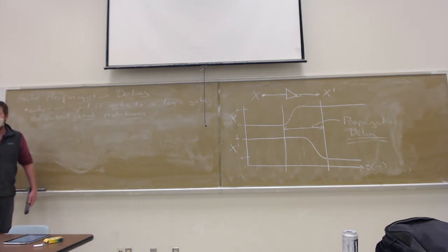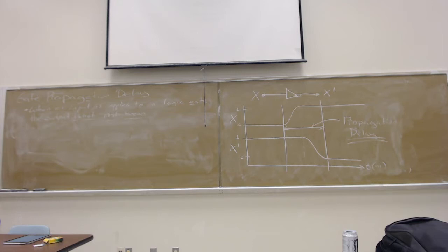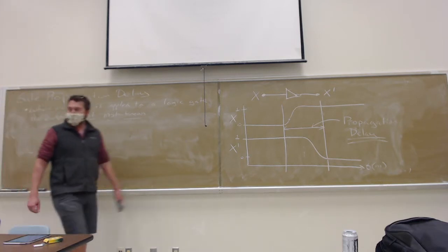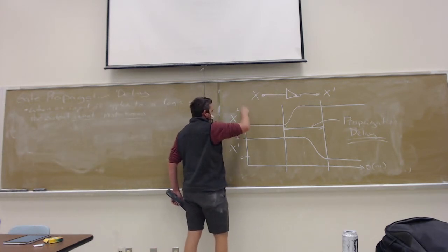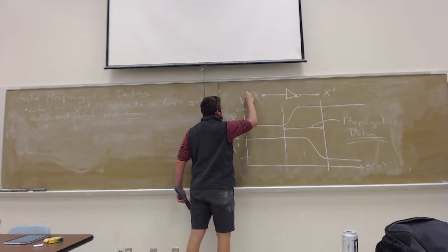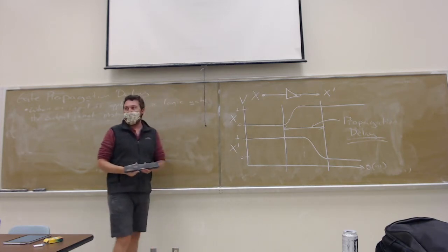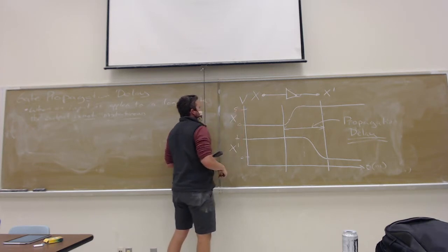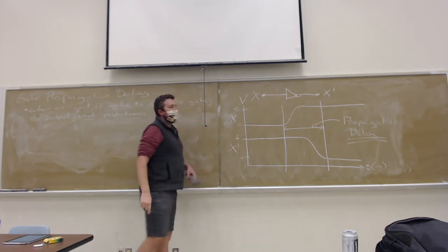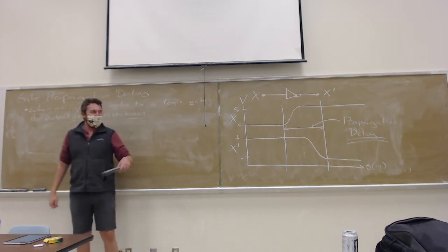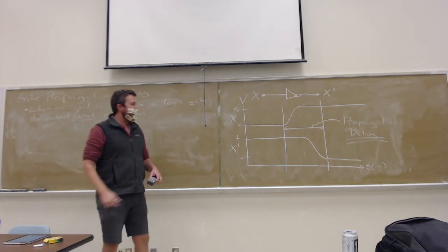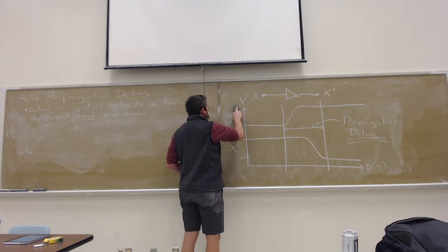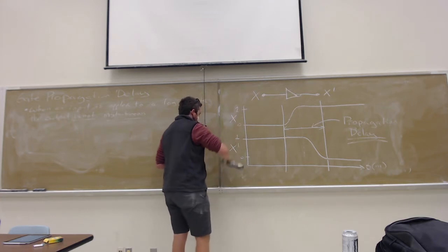So this graph right here is basically like the electricity going through the gate. Exactly, right? We don't usually label the vertical axis, but you could also think of it as the voltage on the circuit, 0 volts to 5. 5 volts is what's commonly used. It would absolutely translate over that, although in modern stuff, it's like 0 to 1. So that's what the propagation delay is, it's actually going through that gate? Yep. Yeah, so it's the time it takes to actually do the thing.